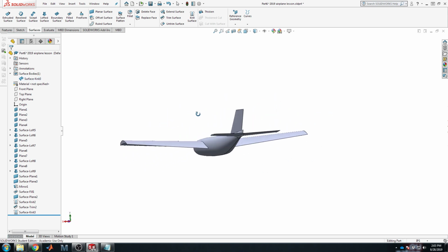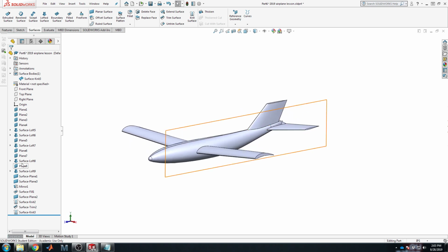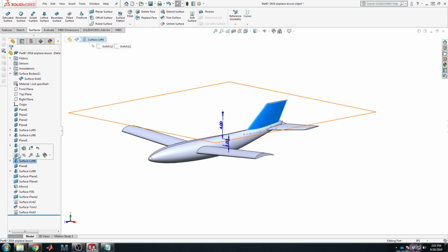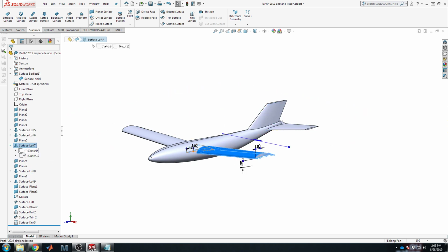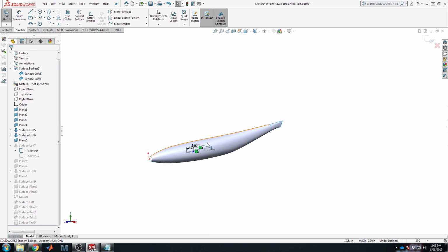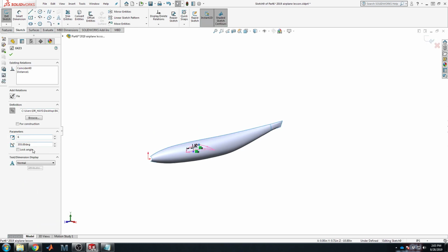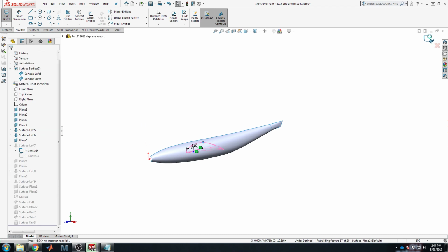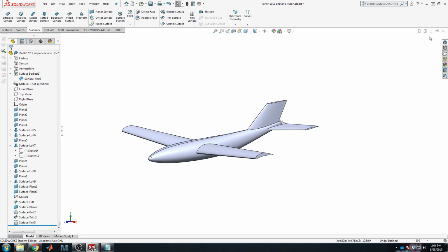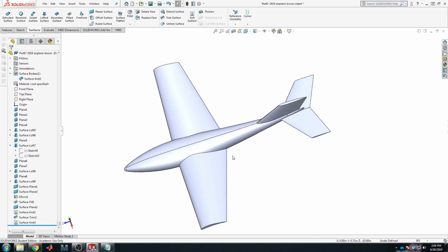The nice thing about this is you can go all the way back in wherever you want. Like, where did I define the wing? Nope, that's the horizontal tail, vertical tail. This block defines the wing. And if I cared to, you can edit this sketch, click on that sketch block, and change the root chord to 8 inches. Accept that sketch change, exit out, and SolidWorks recalculates the entire airplane, showing you the new layout,